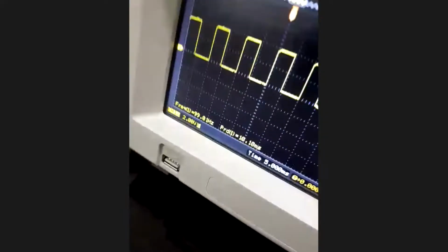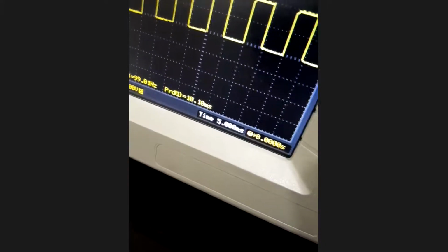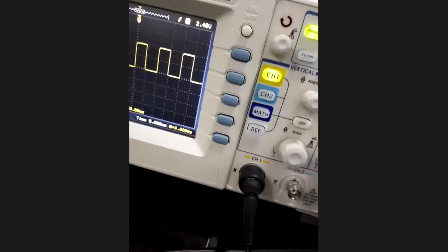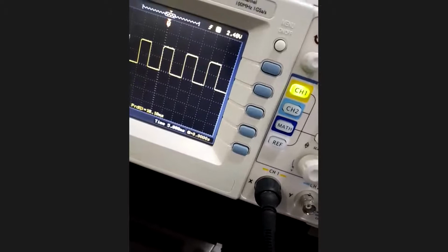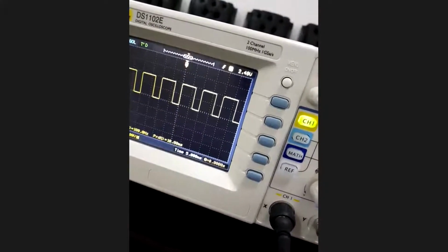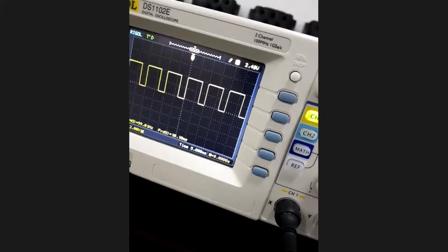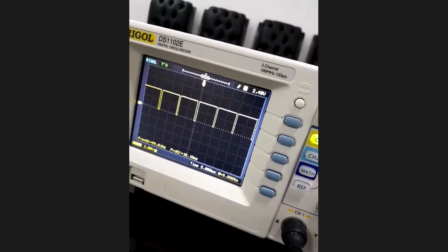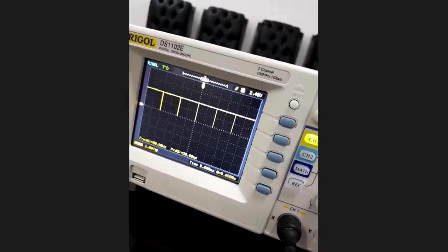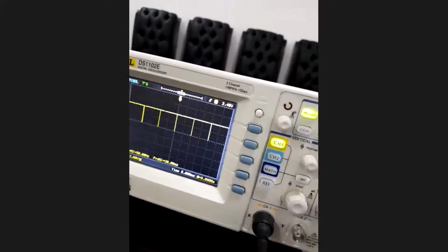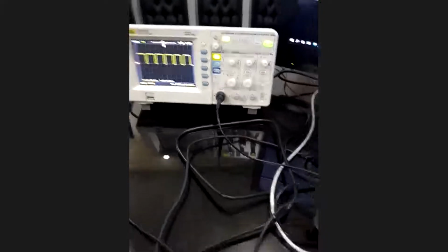Now here I'm in the middle. The PWM signal I have, see the period is 10 milliseconds, a bit jumpy, some noise. And the pulse width, the square here, is 5 milliseconds. So here I'm at 50% duty cycle. I'm incrementing. See here I'm almost at 75% speed or duty cycle. And here is the maximum. Now I'm high all the time. So here is your full speed. So I can connect this to a motor.